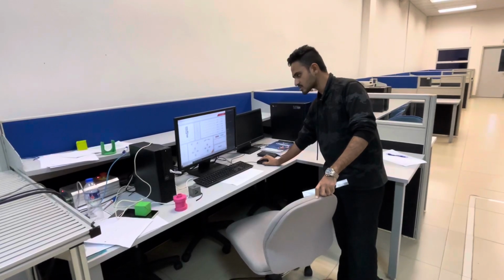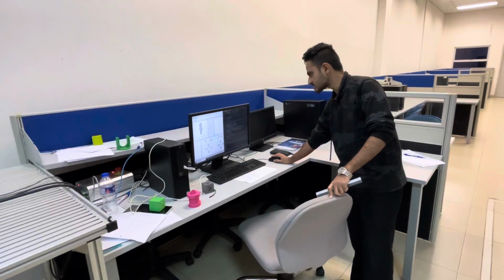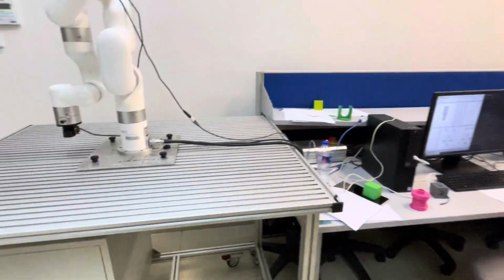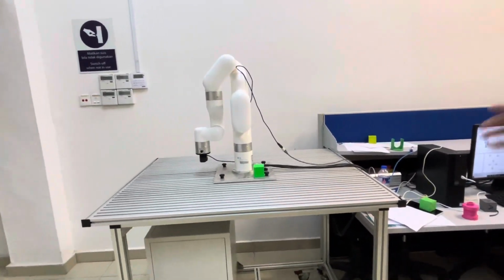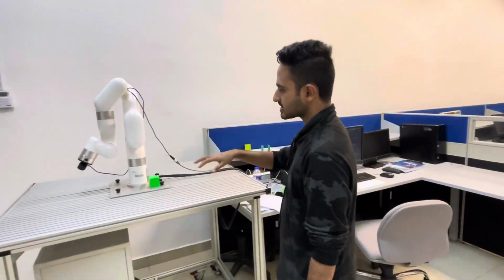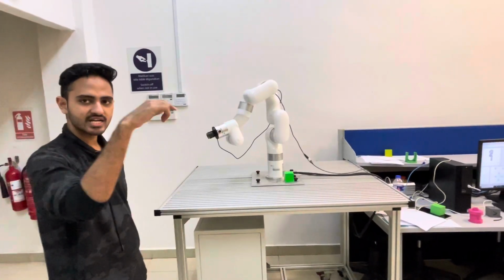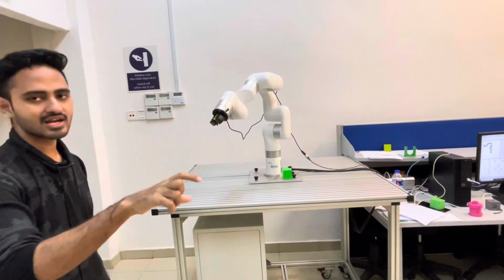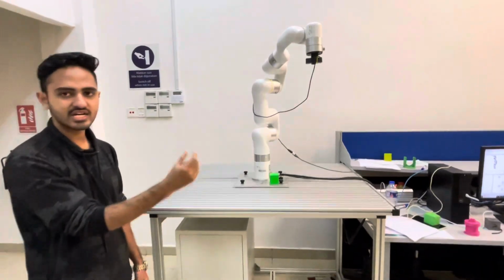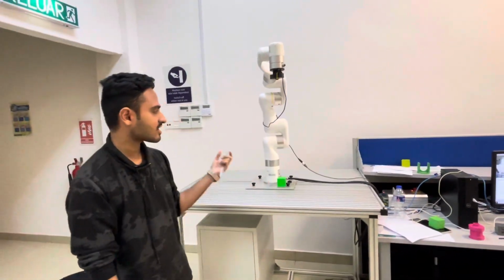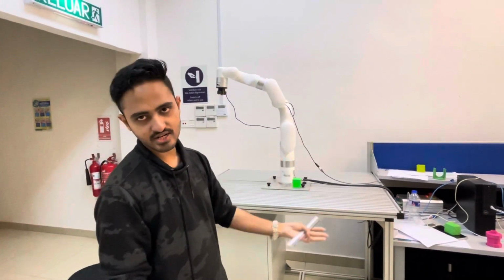First we ensure the robot is in its 0 position, and then we run the Python program, and after running this we place the file somewhat randomly. Now the robot will start moving. It will go to 4 positions and capture 4 images, and then it will analyze and find where the green box area is, and it will calculate the dimensions in the Cartesian coordinate system, and it will give us 3 coordinates, which are x, y and z.